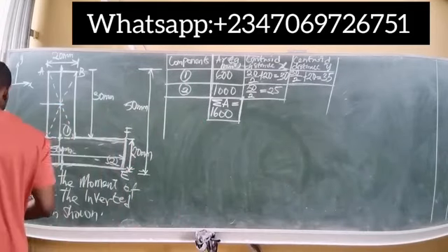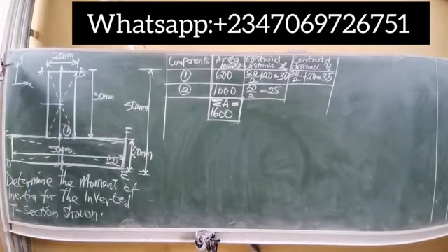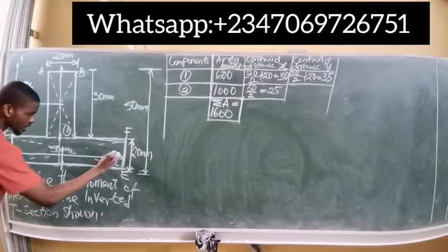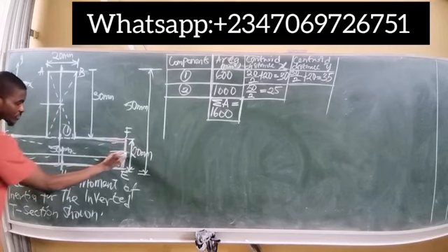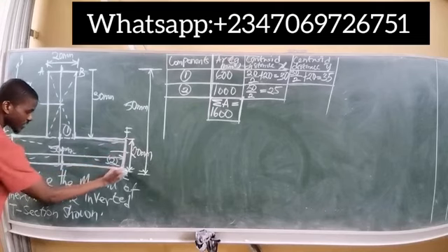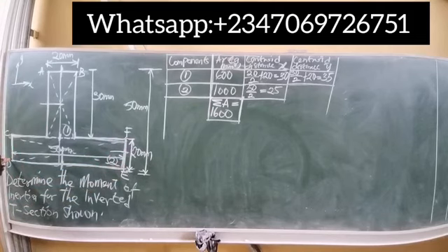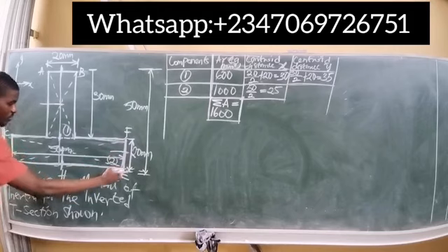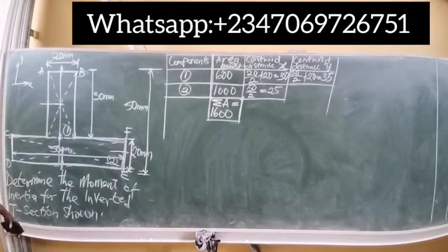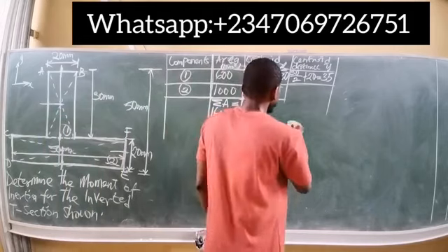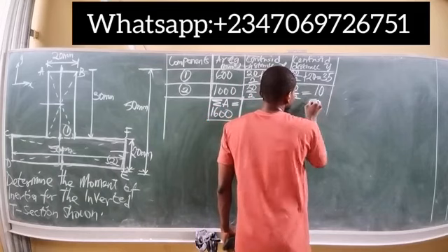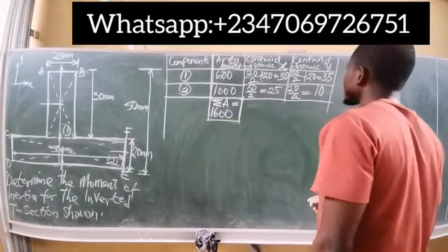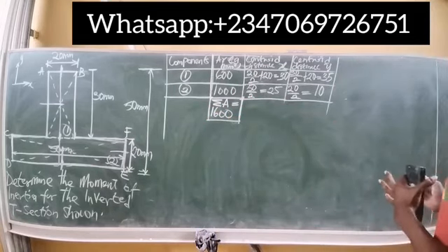And finally, for the second shape, see the same thing. The y segment now is what? Now the depth. And this depth is given as 20. So notice now that if I cut 20 into 2, that's 20 divided by 2. From this top to the middle is 10, from the middle down here is 10. So I'm already at the reference line, needing no other height to get to the reference line. So I simply have the central distance to be 20 divided by 2, and this is actually 10. So this gives me the central distance x and central distance y.